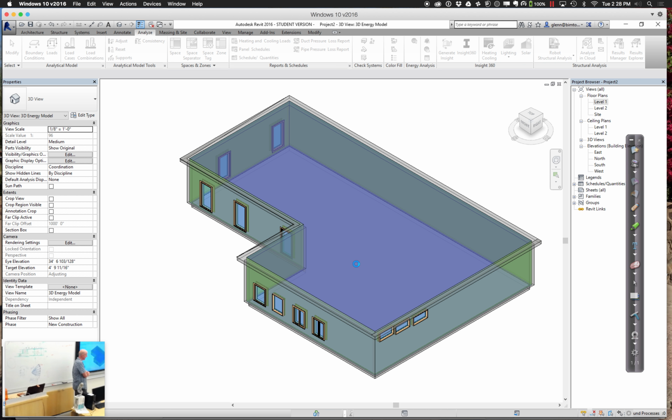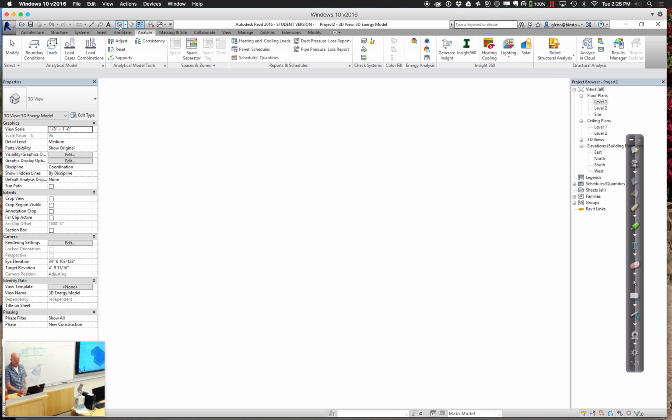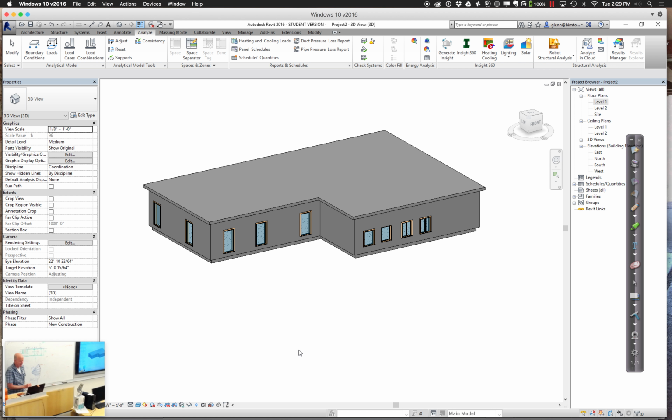We'll do the daylighting and the sun too, so we'll look at all these different things, based on my very primitive envelope so far, but there's enough there to get us going. So, if we want to take a look at this envelope, let me go back to the default 3D view. We wanted to look at the whole issue of the sun hitting the windows. We looked at the sun in a conceptual form, and whether it's hitting the windows. If you want to see what's happening with the solar analysis on your real building model, you can choose the solar analysis tool.